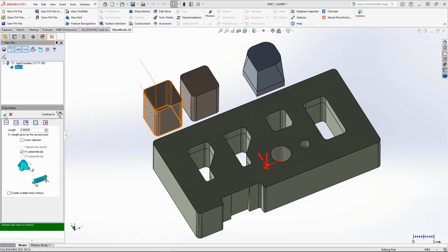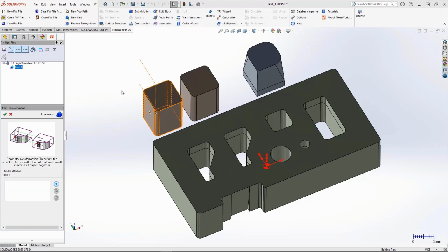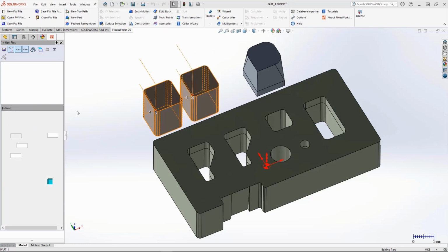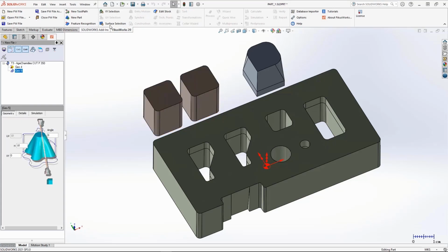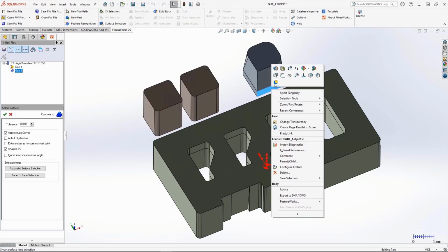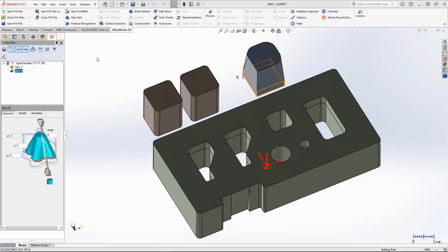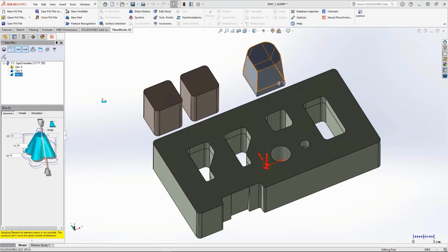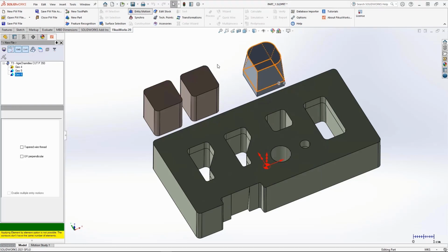We select, in this case, transformations because we have here two punches that we want to have. So we create this transformation, we accept, we add this displacement option. Then we go for the new part, we have another punch, we go for the surface selection option. So the bottom part we select it, then the upper one. So we create the entry motion.